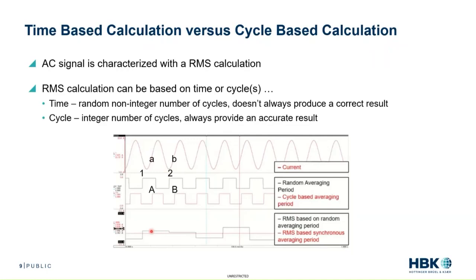On the black waveform result, we see a changing signal because the calculation is based on different fractional portions of the AC waveform, producing an inaccurate result. For example, points between 1 and 2, just eyeballing it, look like maybe a cycle and a third instead of an integer number of cycles.